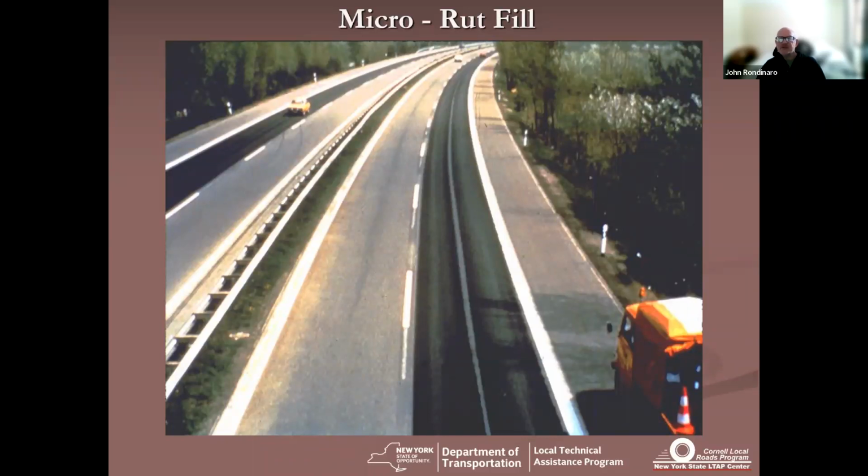Microsurfacing was pretty quick, but it was because they targeted their mix design with the specific emulsions, but the slurry seal was a lot slower. Yeah, they add a polymer to one and they add some cement to the quickset, which helps speed the process.